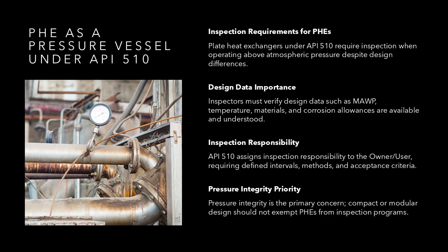API 510 assigns inspection responsibility to the owner/user and requires that inspection intervals, methods, and acceptance criteria be established. This slide emphasizes that inspectors should not exclude PHEs from inspection programs simply due to their compact or modular design, and that pressure integrity remains the primary concern.